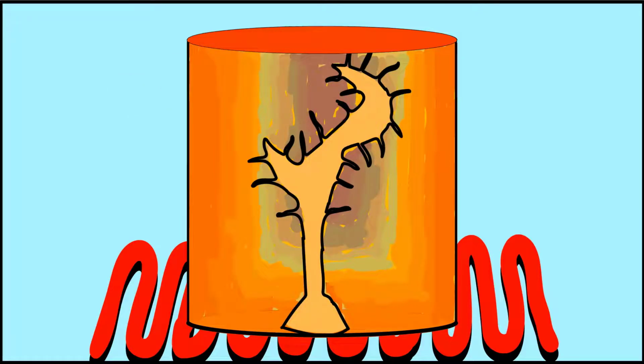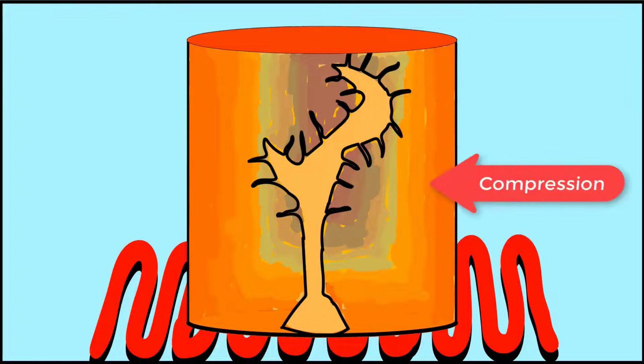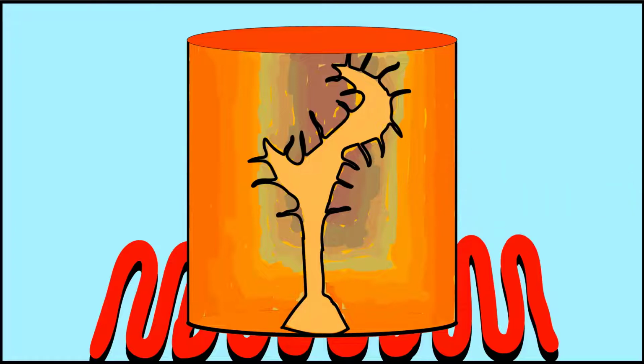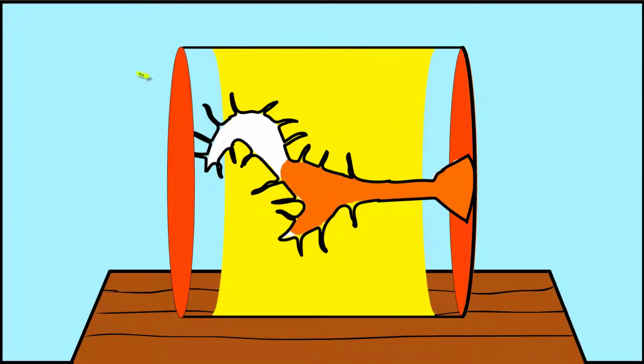And because of this difference in the expansion, the inner wall is under tension, whereas the outer wall is under compression. And this tension on the inner wall, that is the mold wall, leads to the formation of cracking, and this cracking is seen in the form of fins on the surface of casting.